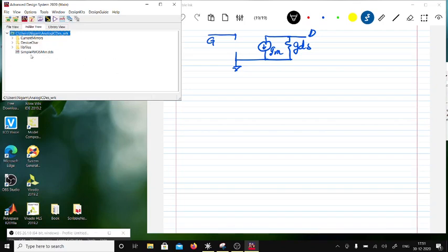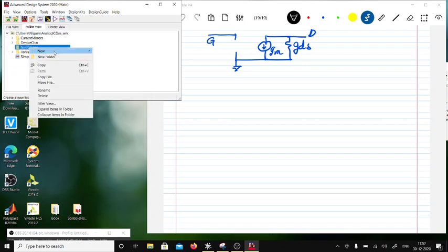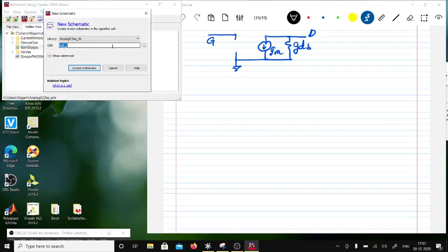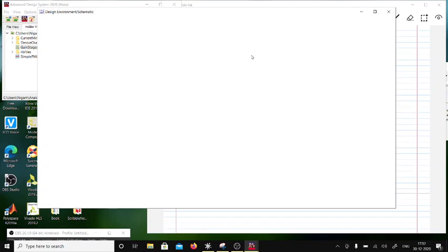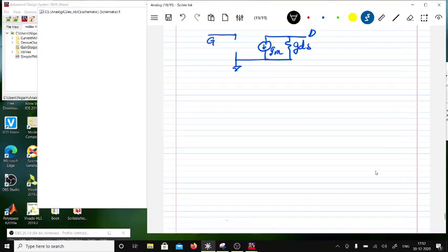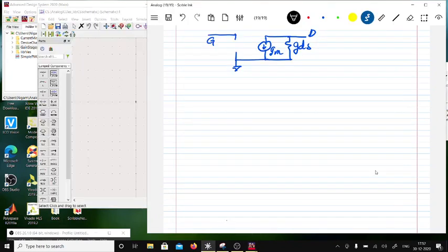So I'm going to do a little bit of practice and a little bit of theory. Let me make a new folder here and call this gain stages, correct? And then in this gain stages folder, I'm going to talk about three amplifiers. One would be common source. So let's create a common source amplifier. Let me try to explain how this common source works, because now we have a small signal model, so we should be able to see what a common source is.